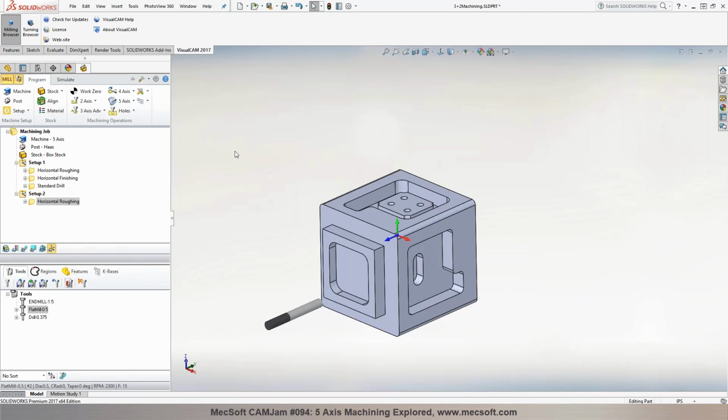In this particular case, we are looking at a head-head configuration, which means the part would remain stationary, the orientation of the tool would change to be able to program from this particular orientation. Now, if it's a table, or a table head, the part would be rotating on the machine. So again, it depends on the type of 5-axis machine configuration you currently have or your customer is going to be using.